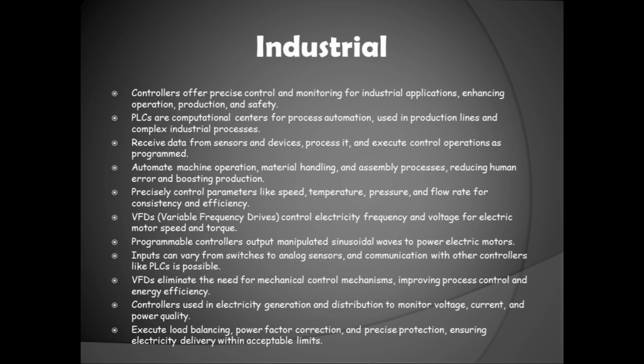These devices' controllers can be programmed by technical personnel, and their output is in the form of manipulated sinusoidal waves, which powers electric motors. Depending on the VFD, the inputs might vary from switches that determine its method of operation to analog sensors that change the frequency and voltage according to their measurements. Furthermore, these devices can be operated via communication by other controllers such as PLCs.